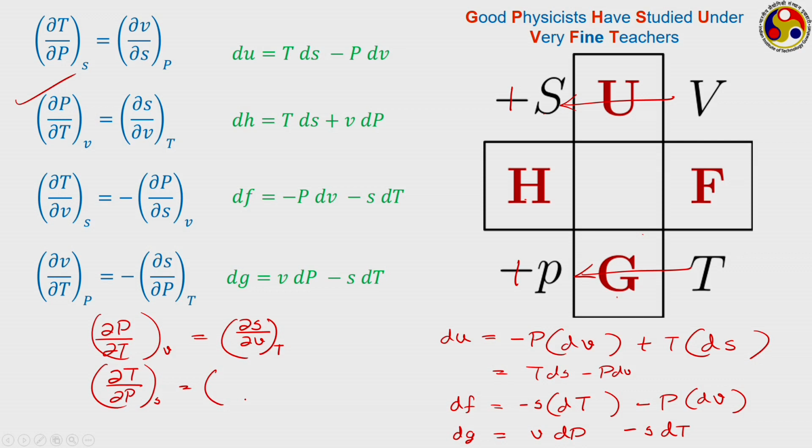We are moving along the horizontal line from the right to the left. So, we have started with t and moved to p. So, go to the parallel row, which is ∂v/∂s, and the subscript will be the one opposite to v, or the diagonal opposite to v, which is p, which is the first relation. So, this way we can develop or recover 2 of the relations.